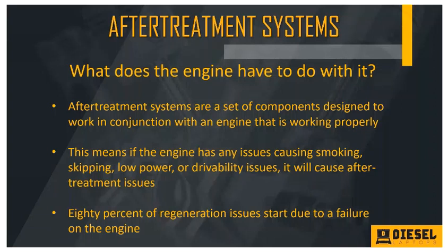Now, just a fun little fact for you, 80% of regeneration issues start due to a failure on the engine. Now, that doesn't mean that sensors don't fail. That doesn't mean your exhaust thermistors aren't reading bias. That doesn't mean that your diesel particulate filter differential pressure sensor isn't reading bias. That's not what that means. Obviously, sensors do fail. Obviously, components do fail. But 80% of all regeneration problems are happening because of an engine-related issue.